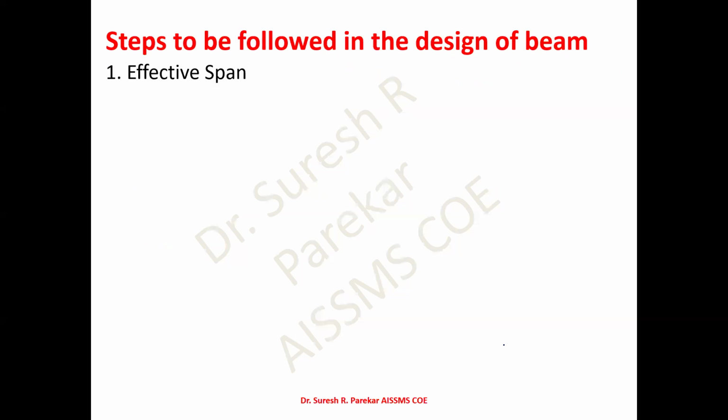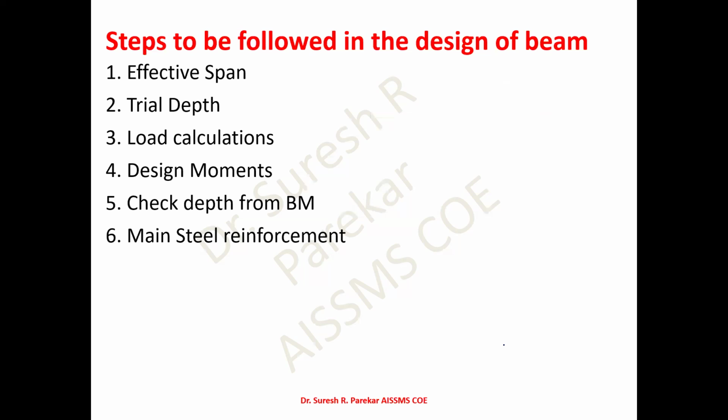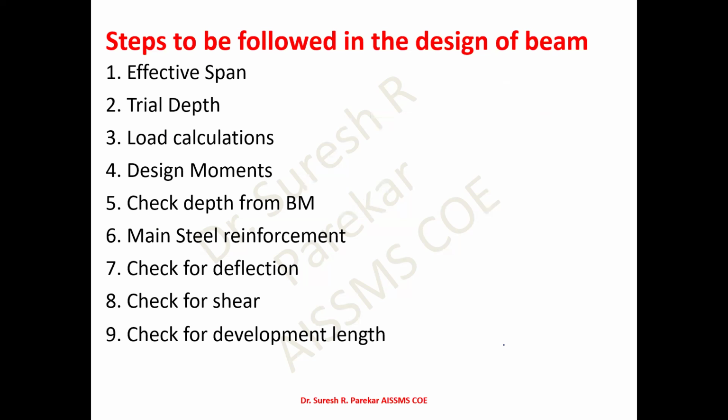So, steps to be followed. First, effective span, same as your slabs. Second, trial depth. Third, load calculations. Fourth, design moments. Fifth, check depth for bending moment. Sixth, main steel reinforcement. Seventh, check for deflection. Eighth, check for shear. And ninth, check for development length.